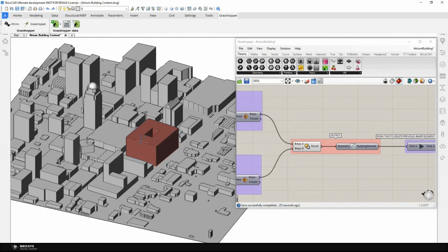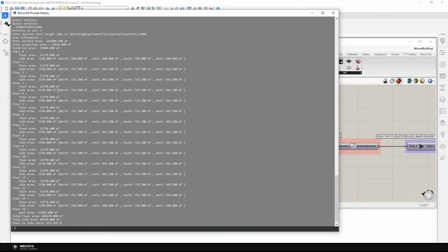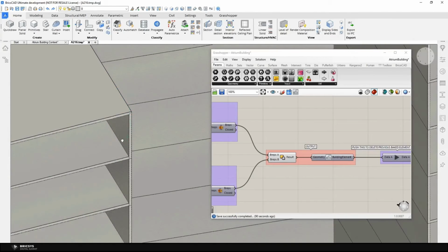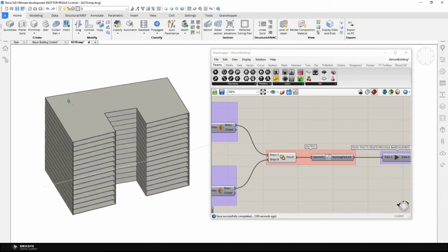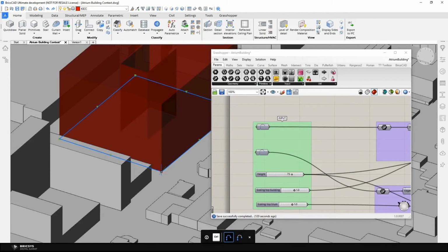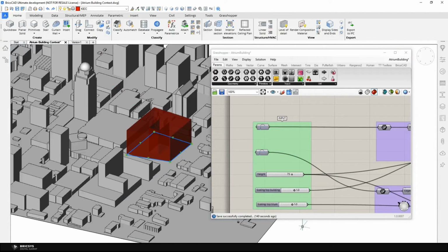Once a milestone has been reached, we can isolate and quick build this variation and harvest a lot of useful information, for example, footprint area or floor areas, as well as quantified building elements based on the original shape generated with the help of Grasshopper. Then we can go back to the original design and iterate further using both direct modeling and Grasshopper.